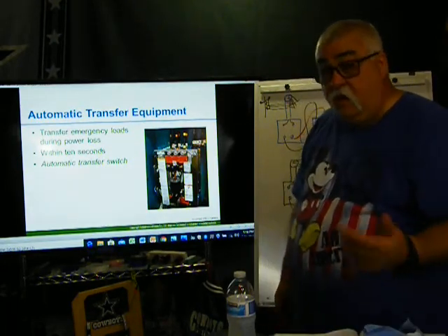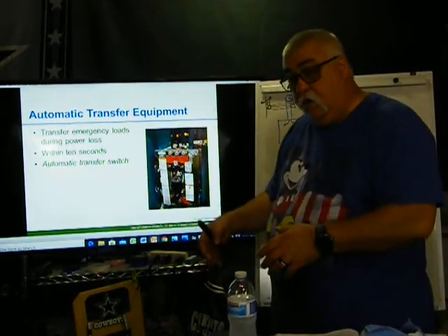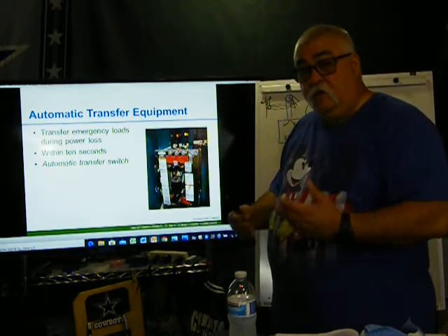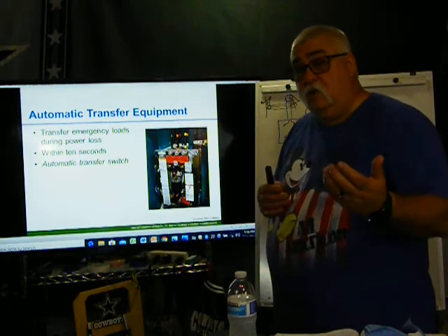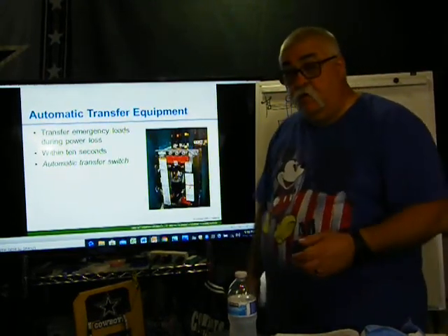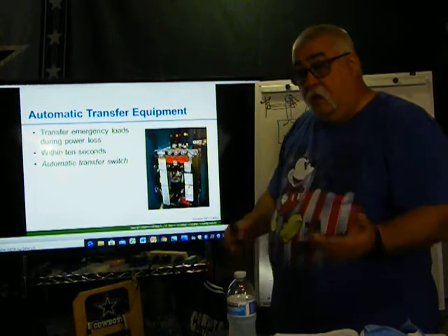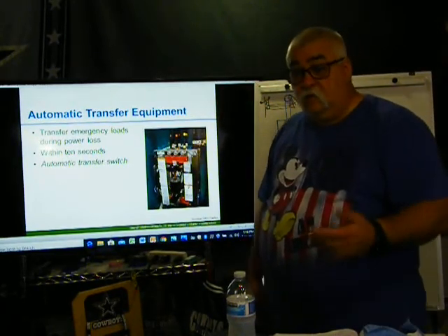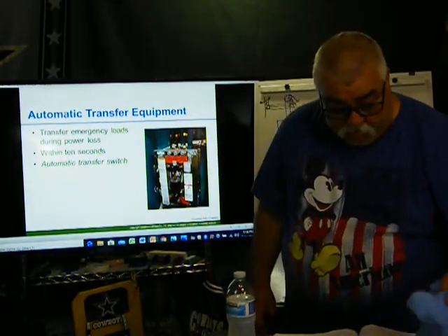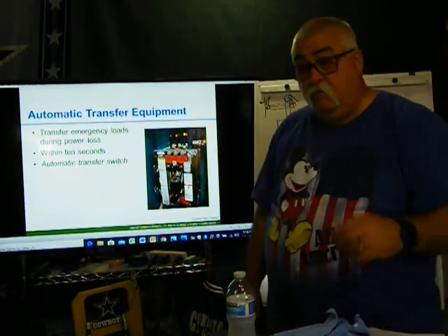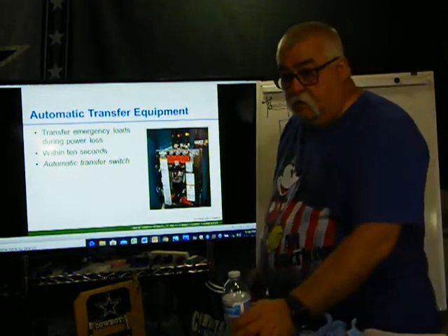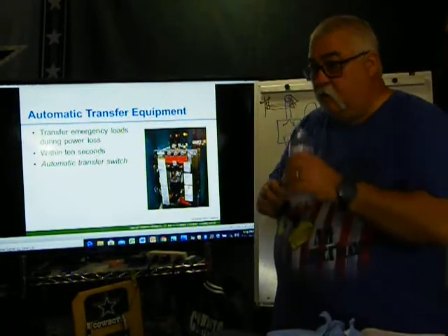A lot of them have heaters within the generator, if it's a diesel or gas generator, so they keep it at a certain temperature. The engine does not have to heat up much because it's already hot. Running temperature may be 220 degrees, so they keep it at 180. It doesn't take much to heat up, but it can still transfer over instantly. At UCLA, things transfer over within 6 seconds. In a hospital, you don't want people to be down too much. People start freaking out.